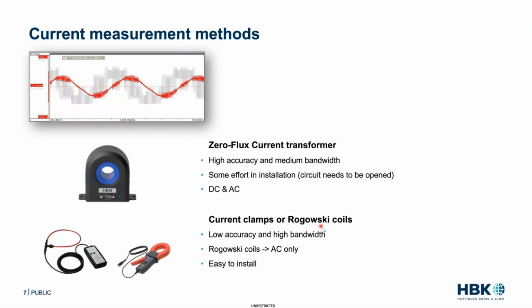Rogowski coils are really good for getting into areas you can't usually fit. For the high accuracy characterizations, we advise the flux gate. Again, these have bandwidth limitations. Sometimes they introduce a phase difference. Anytime you introduce a sensor, you're introducing more inaccuracy. So just some things to consider.